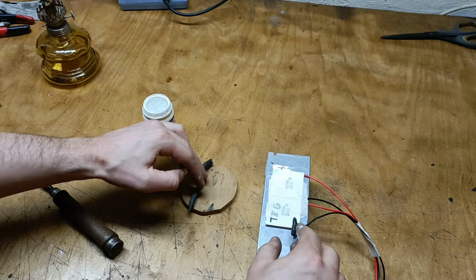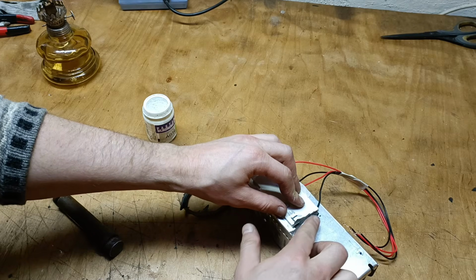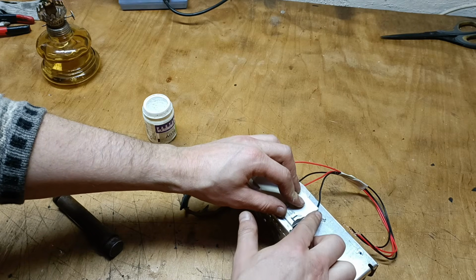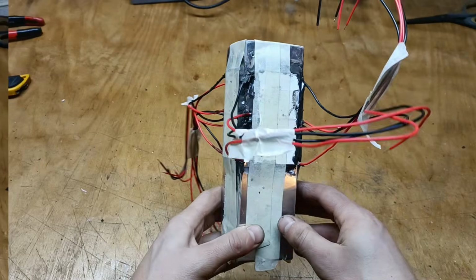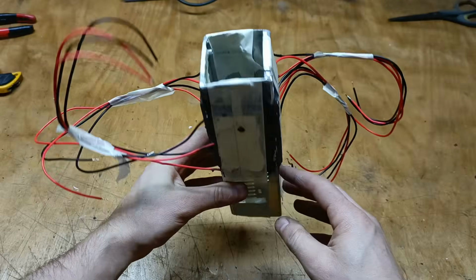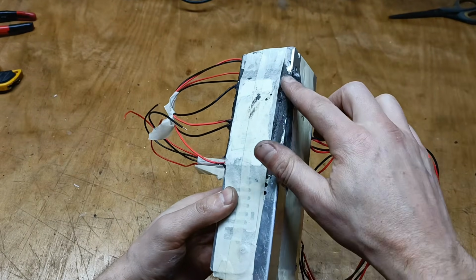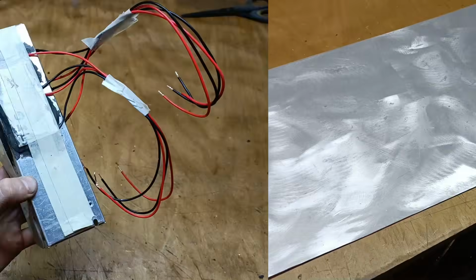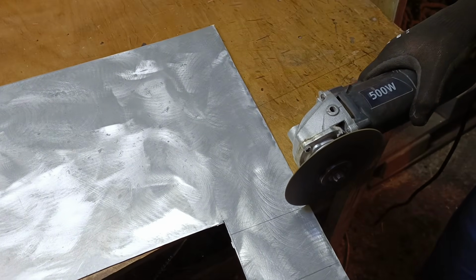But of course the thermal paste doesn't adhere the cells to the structure itself. This is achieved using a high temperature resistant adhesive. This is what the construction looks like with all 8 Peltier cells glued in place. As you can see, the cells are secured with adhesive tape until the glue dries, and meanwhile I can start making the heat sinks, the key elements that will absorb heat from the Peltier cells.